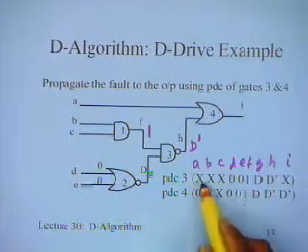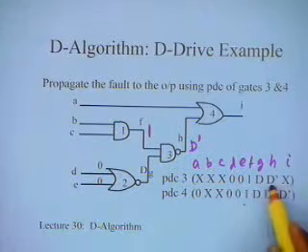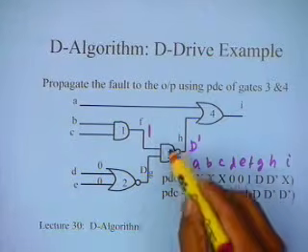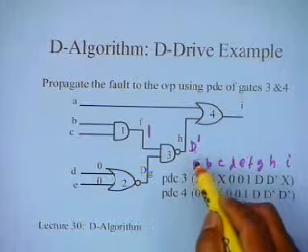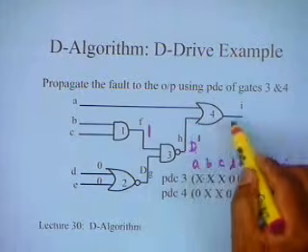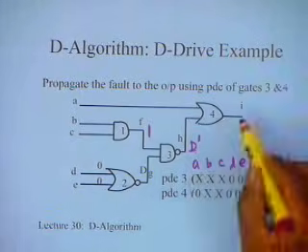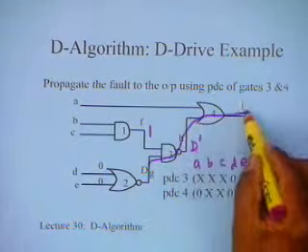And when I cross it, I get 0, 0, 1, D, D complement, X. So now I have got this D up to this, D or D complement does not matter, the fault is transferred here. Now I have to transfer the fault to the output, because this is the path, please remember, I chose.